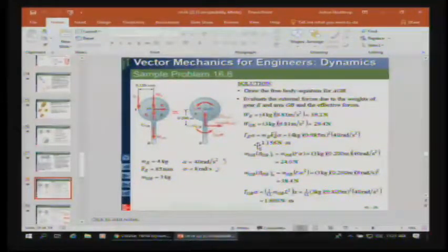We've never really dealt much with mass moments of inertia. We've talked about areal moments of inertia, but when we get into this type of motion, we need to just extrapolate our discussion to mass moments of inertia. Although I would suggest that the extrapolation is not very much. It's just that you use mass instead of the area of the shape. And we're not going to go through the derivation. But it works the same way, and k is just a radius of gyration. So in that case, we can come up with that vector, which is going to be in Newton meters. It's interesting to note that Newton meters is also the unit of either energy or torque. So everything kind of fits together in terms of a gear train.